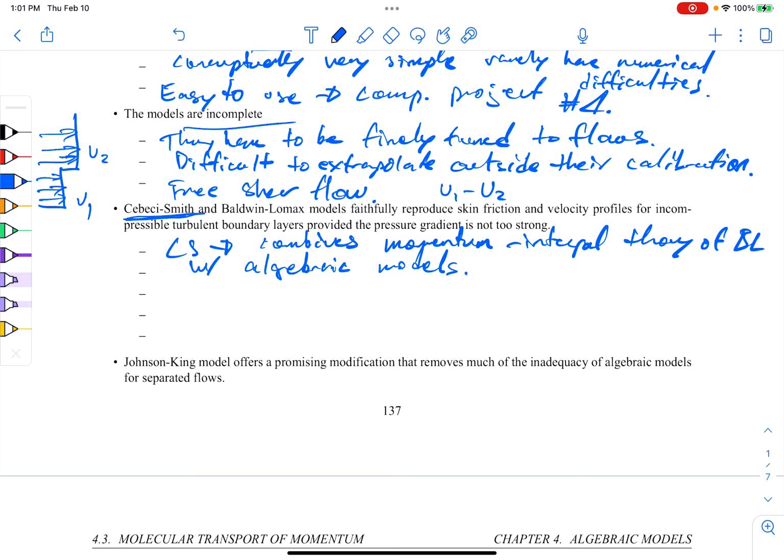But it's sort of limited, and in the original models, you actually needed to know something about the boundary layer. You're tracking boundary layer statistics like thickness and momentum as you calculate the boundary layer. And that's something you might even need to prescribe in advance to get a solution. But it's practical, and it did great results for compressible flows. Some of this was overcome and generalized into a more or less incomplete model, I suppose you would say, by Baldwin and Lomax. And that's the next paper we'll probably look at.